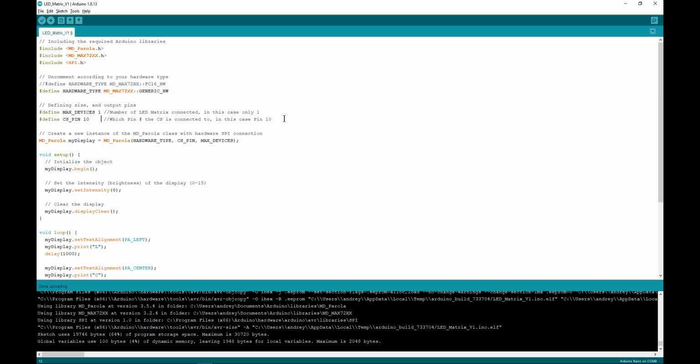Most of the pins that we use for SPI, you can't change, except for the chip select pin. I put that as 10. You can easily move that to another pin, for example, 8 or 9. But since we're using SPI, I prefer to keep it as 10 since it's generally faster and more reliable than using a data pin. Just so you know, if you have to, you can easily change it.